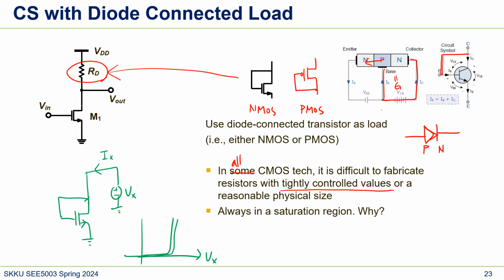It's like this. Because of VGS, it's kind of looking like a diode, because the ideal IV curve of a diode is just this, right? At the VT threshold, the turn-on voltage, the current just suddenly increases. And for this NMOS, the current is not dramatically increased, but still we have a VTH here, and then the current increases with a square law. So again, the current profile of this diode-connected load looks like a diode too.